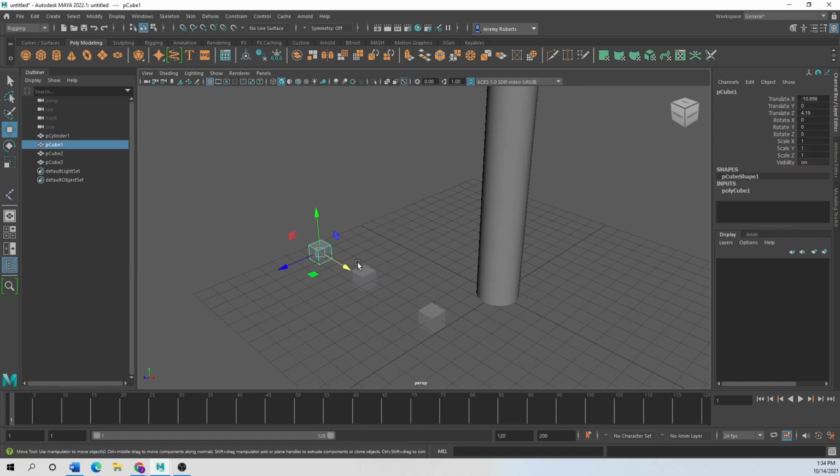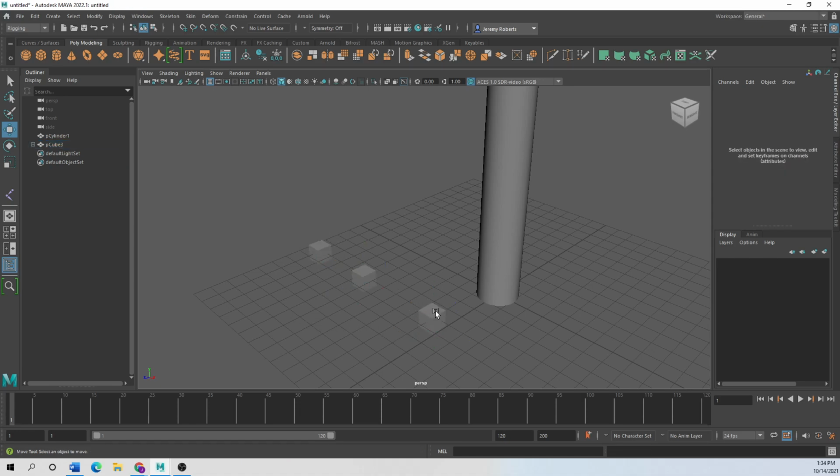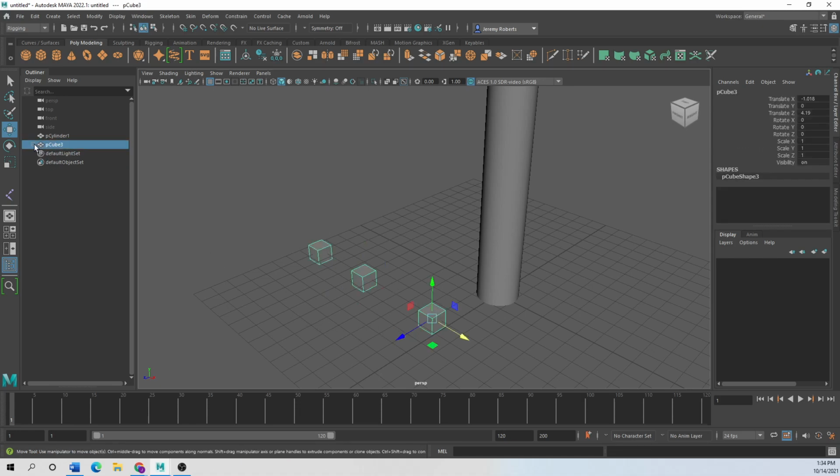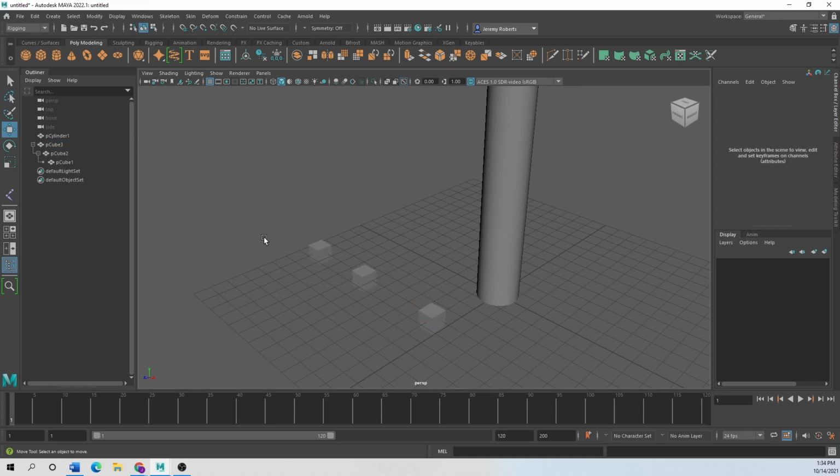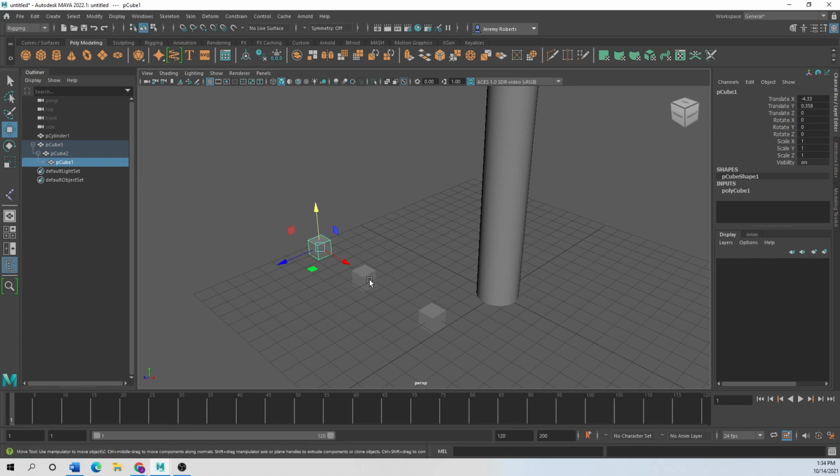You can shift select the next one, press P, shift select the next one and press P. Now basically, instead of grouping these items together, if you look over here in your outline, they've created a little structure to where everything's running down. This can work independently because it's the tail end one, the very small child. In other words, I parented that one to that one, then that one to that one. But if you move this one right here, now all of it will move.